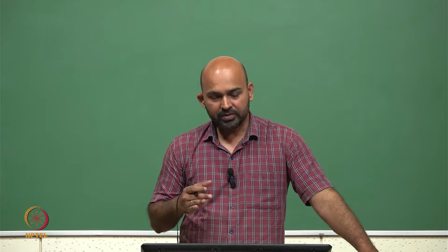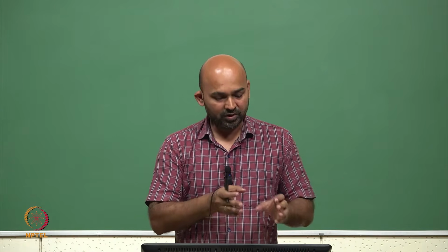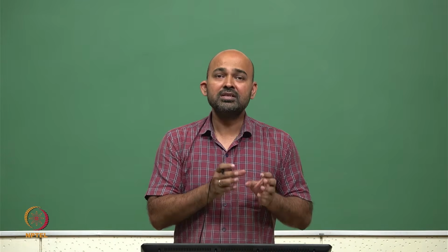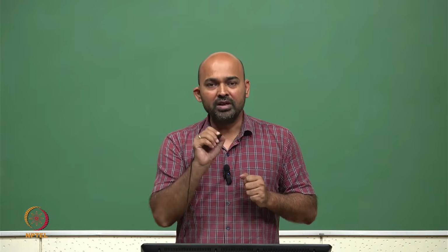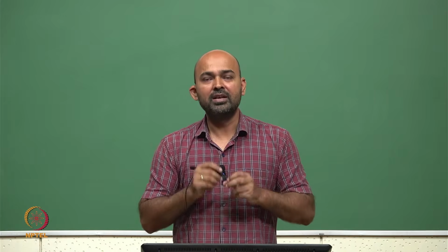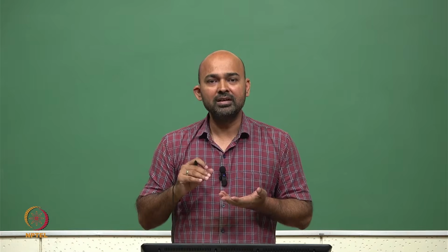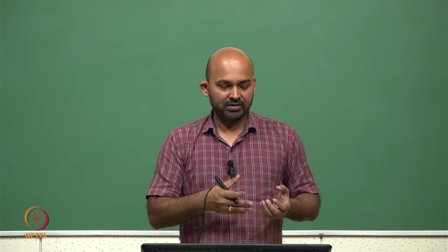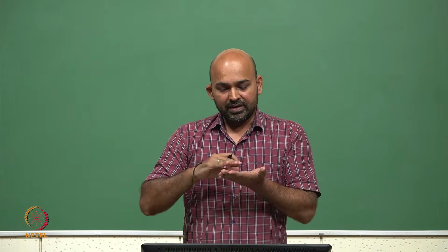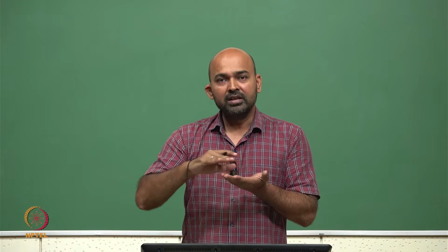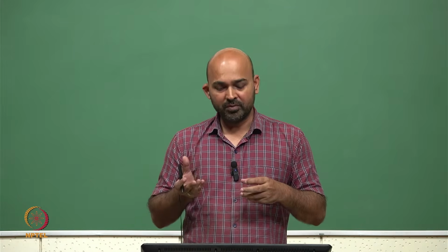Let's see how a CMOS inverter looks at the silicon level, because right now what we drew is just the schematic, which is a symbolic view of an inverter. This is how we understand a device PMOS and NMOS. However, in actual practice, when we are going to fabricate on silicon, this is not how the inverter or the device looks. In the substrate or the silicon, we look from the top, which is something called a layout of the MOSFET.